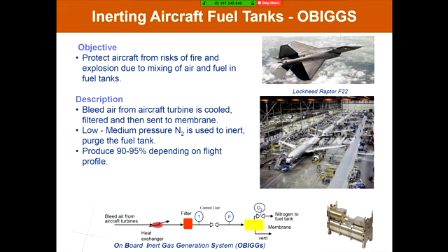However, you would like to have as much permeability or as much flux as you can get, because with a membrane that has twice the flux of an existing one, you can make the system half the size, because you only need half the membrane area. And in applications like this, space and weight are critical, and anything you can do to reduce the space and weight can make a huge impact on cost. And so with that in mind, we have worked with scientists here at CSIRO and also